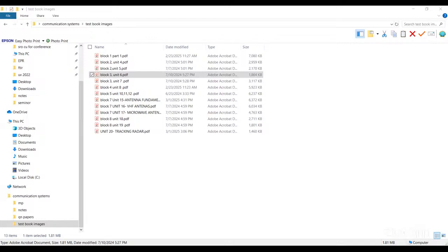What information is given here? Traveling waves propagating in a directional coupler are shown in figure 6.3. A fraction of the wave energy incident at port 1 passes through the holes and is radiated into the secondary waveguide. Why is it radiating into the secondary waveguide? Because there is a slit. So these hole slits act as which antenna? A slot antenna.